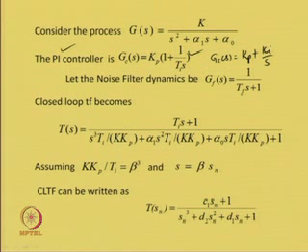So, we have got a different parameter here, Ti in place of Ki. Ti has been introduced in place of Ki. This has been done intentionally for ease in analysis of the closed loop transfer function. One can make use of the earlier form, of course, with some difficulties.